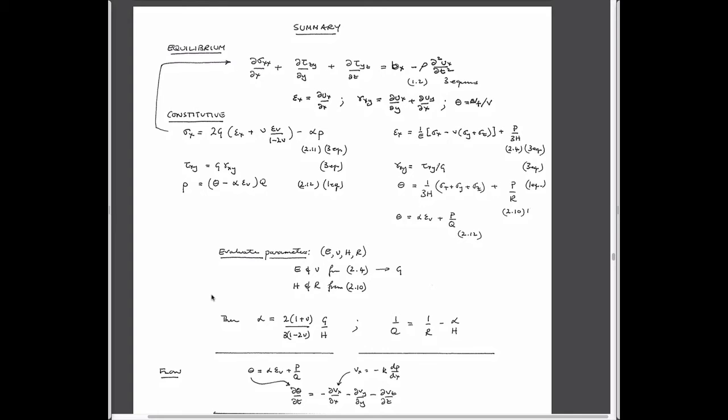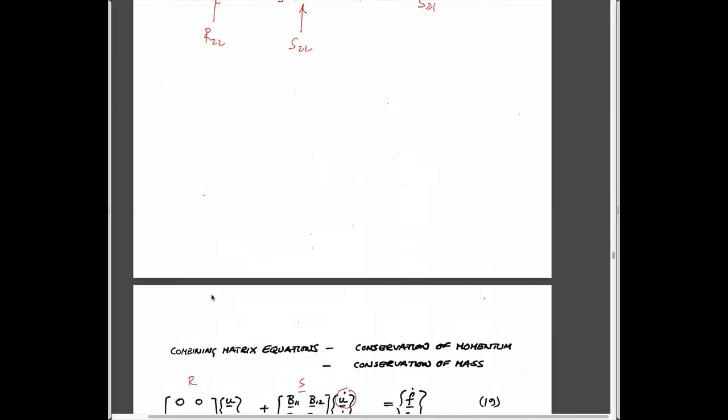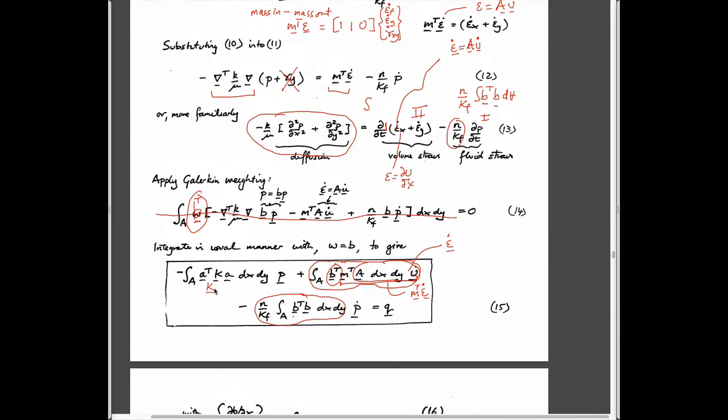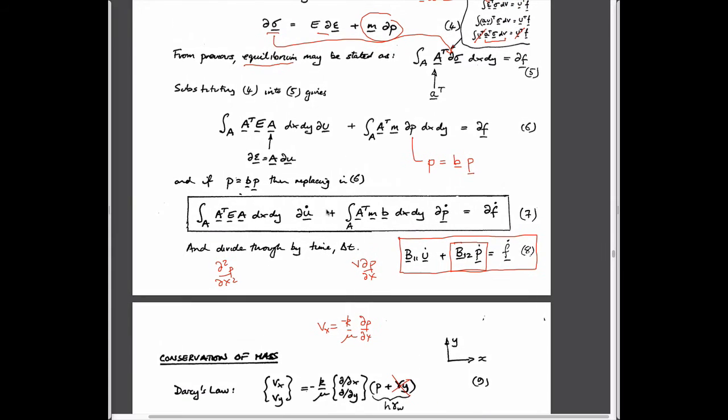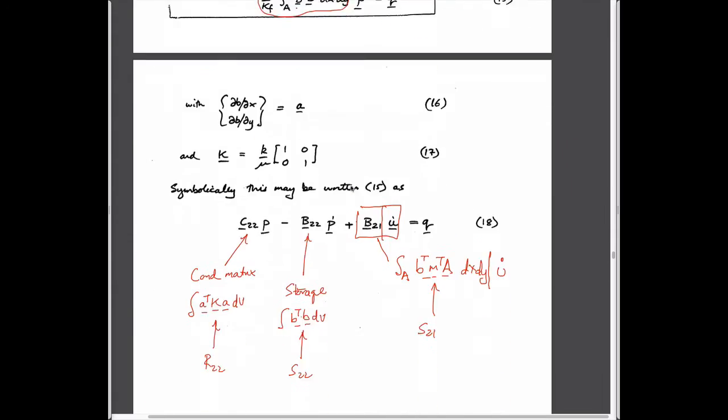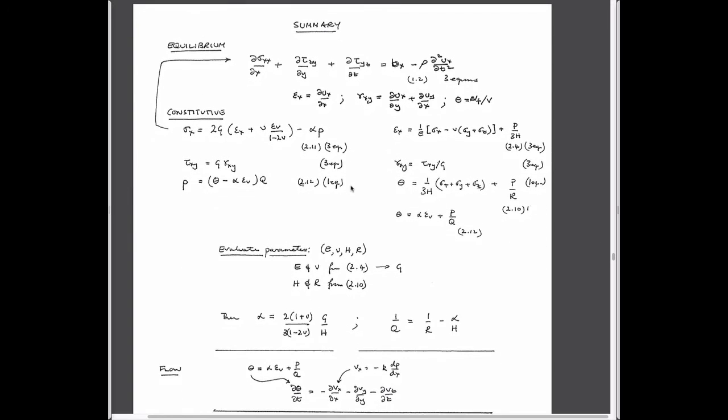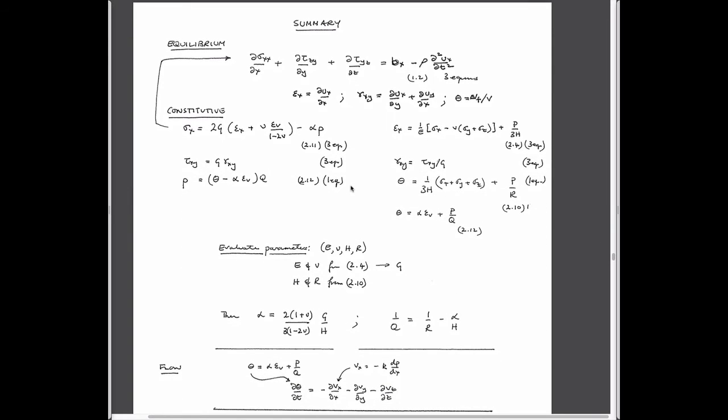I suppose, no, actually, in this, the one thing we don't have, as we look back through here, we certainly have a finite element statement or a PDE statement inside the brackets for the flow equation. So we absolutely do have that, which includes the effects of strains. But if we look at the solid mechanics expression, we really only have the finite element expression from the way we did it. And we don't have the component PDE. But let me walk through this. And what I'd like to do is walk through this and then see if we can make it work in COMSOL, or at least open it up in COMSOL to show what the individual terms should be.